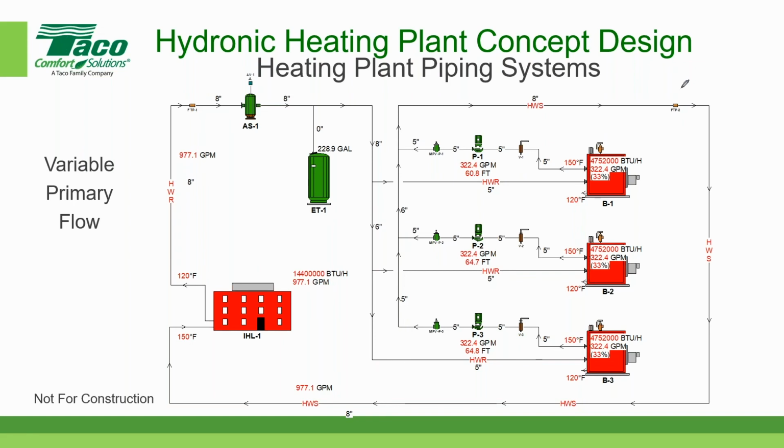Was there another question? Yeah, I think this would be a good time to mention that maybe this drawing is for presentation purposes. People are commenting on some of the locations of stuff. Yeah, so if you notice in the left-hand corner, it says not for construction. So I decided to add that disclaimer in there for that exact purpose that you're talking about, Brett. So yeah, well, yes. I mean, you've got the expansion tank and air separator located in one spot. Maybe you're pumping away from the boilers. Maybe you should pump to them. There's all different kinds of stuff there.